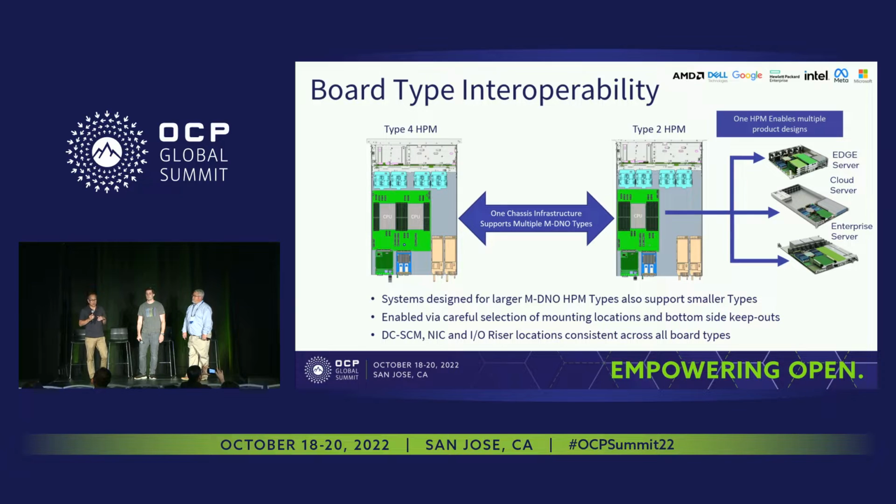That allows us, if you want to optimize chassis depth design, to use either Type 2 or Type 4. The benefit of Type 4 is it gives you more I/O as well as more lanes and processor core count that can optimize for an accelerator head node.